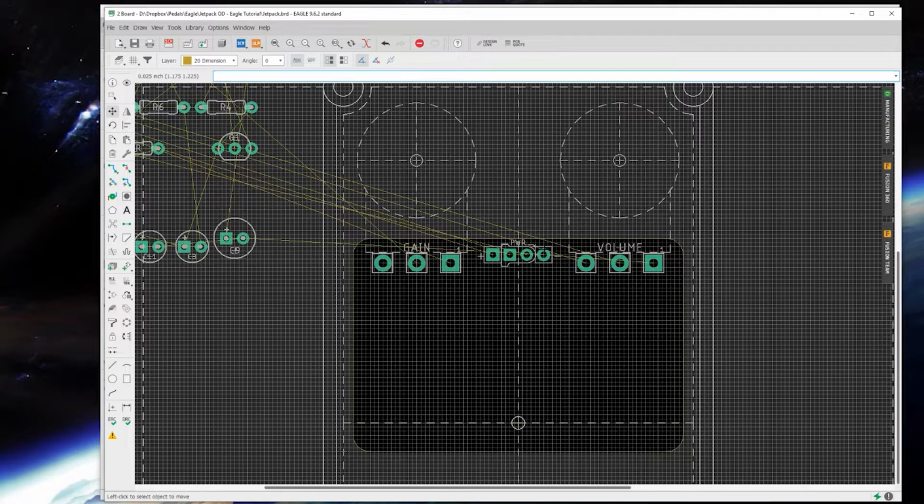There's a big plane of copper, and then the traces are within that, and that plane is the ground plane. That's what everything connects to that goes to ground. I do the same thing for fabricated boards, but since we have 2 layers we can play with, I make the top layer the voltage rail, the 9 volts or whatever.